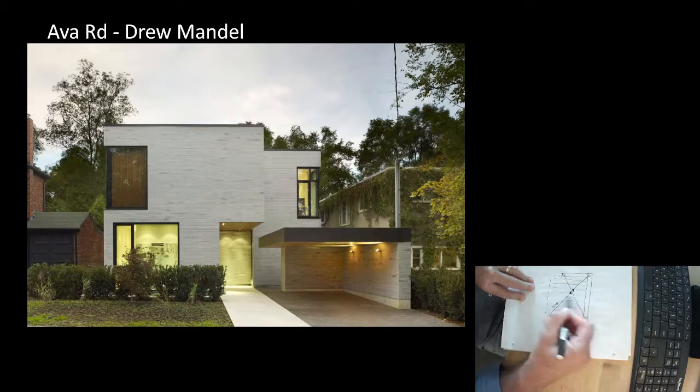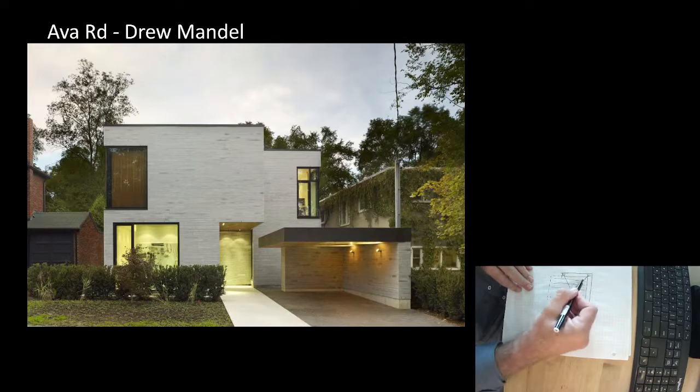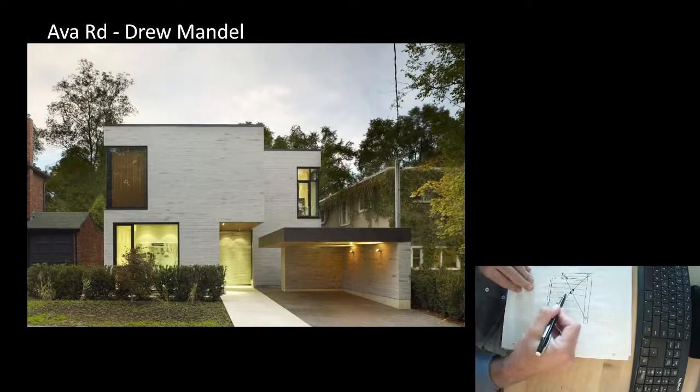These ones cantilever over. Oh, actually, no, they didn't. What Shannon did then, come to think of it, is further filled in with steel, so that the wood joists could live in the same plane as the steel and keep things fairly shallow. So, is this the only way to do it?